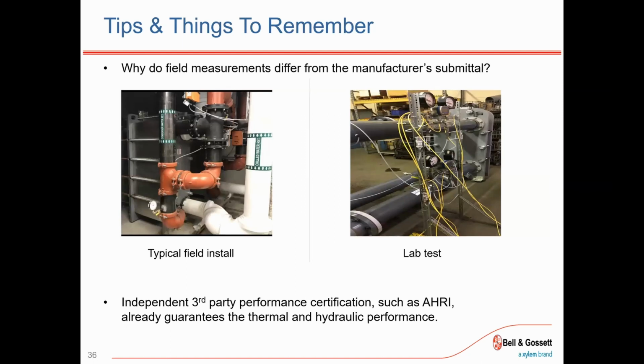Now, I just have this slide here for considerations: once you approach that 2-degree approach temperature, your surface area gets exponentially greater. I see people try to do even tighter approach temperatures, but once you're beyond 2, you have to start thinking about how this is even going to work in the field. How can you even verify this is accurate?